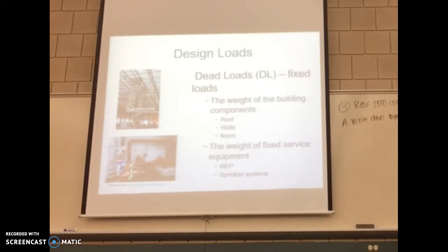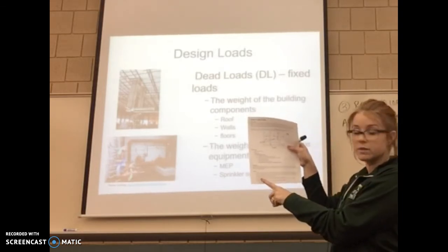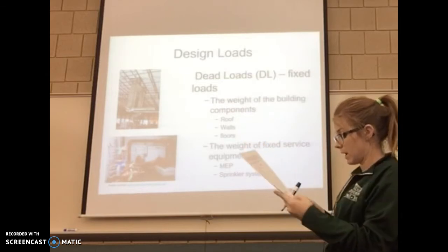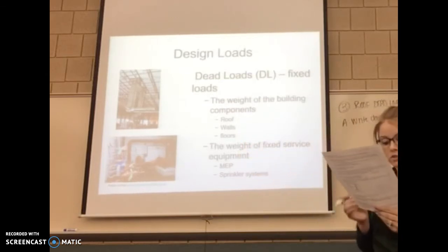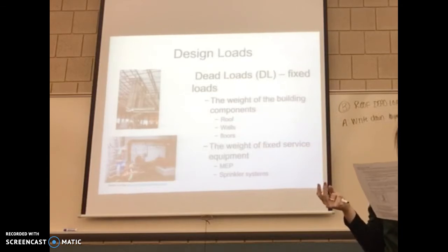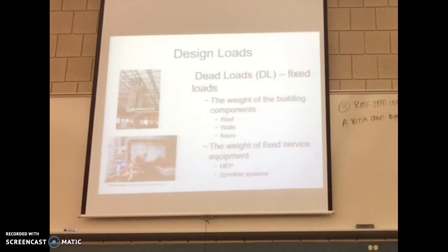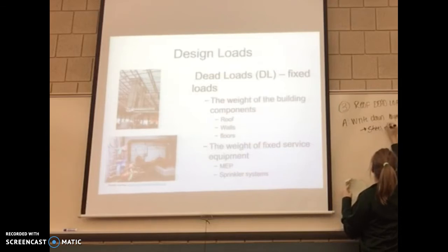Okay? So to find the layers of our roof, you have to go to the criteria part of your activity and read through there. So it says the first criteria: our low slope roof will be constructed of a steel deck, 5 inches of rigid insulation, and a built up roof, BUR. Okay, so first one is a steel roof deck.